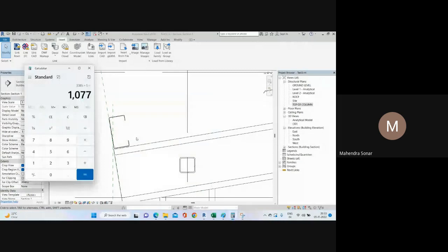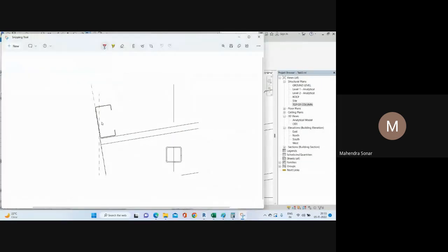So in that case, we can add one equal angle here, like that. This angle is welded to the top of the rafter, right? And you can give the shim plate here, and you can give the bolt here. So this connection looks like that. Okay, and after that we can add the gutter here. So the gutter connection you can just add like that.